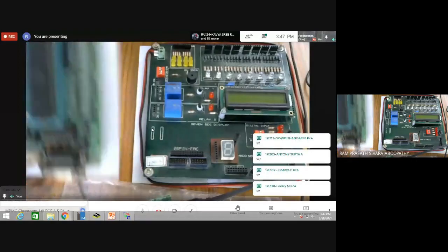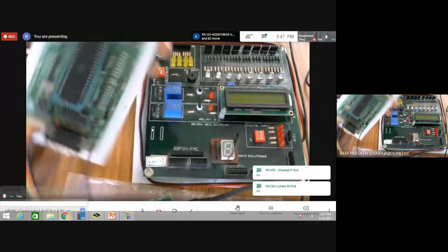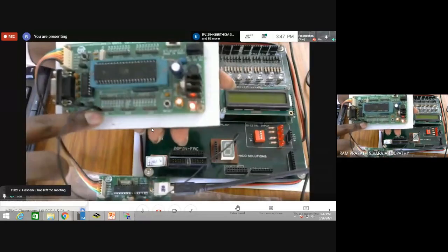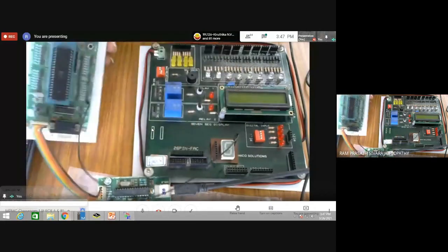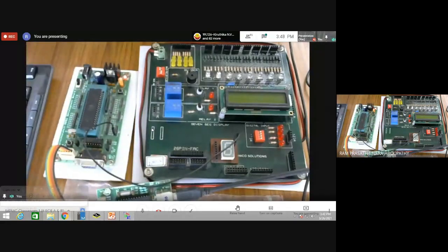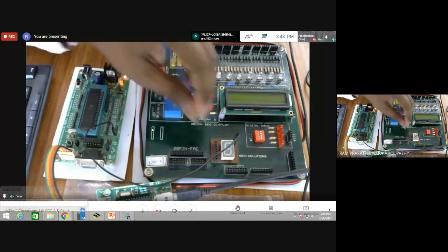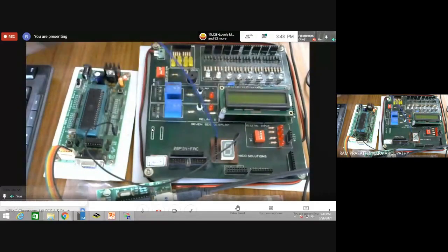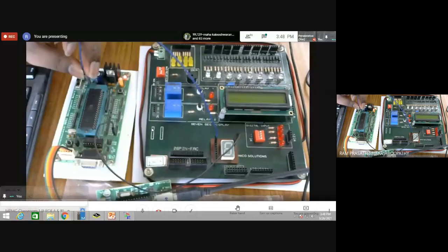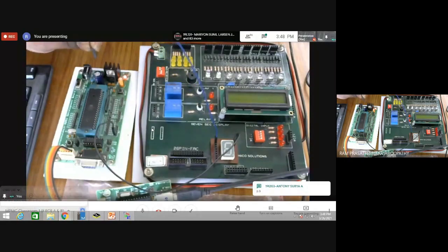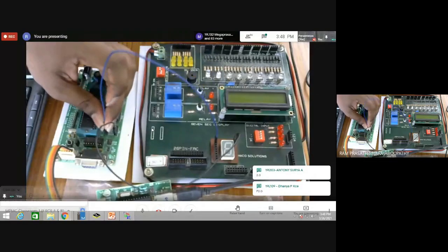Fine. Can you people see it? So here is the 5 volt pin. So it is connected here. Fine. Then the remaining pins, see. The very first pin on the 7 segment LED is on the left hand side, right? The first pin is A. Where do we have to connect the pin A? In the hardware configuration, where did we connect segment A? Yes, P2.0. Very good. What about the next pin?